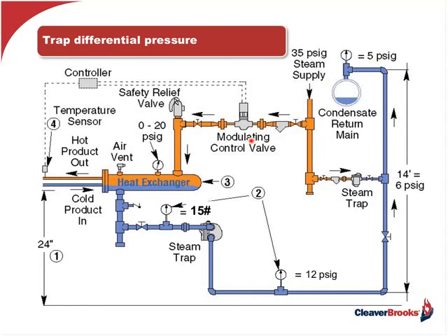And based on the operation of the trap itself would then dictate whether or not the trap should either be rebuilt, like in the case of a thermodynamic trap, or whether it should be replaced. But to say, as a gross overall statement, to replace these or rebuild them every year, I think that's a bit extreme.